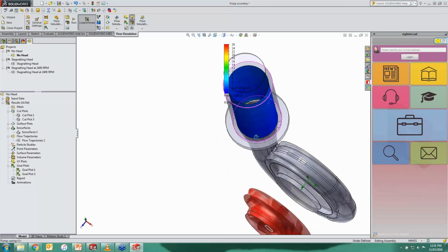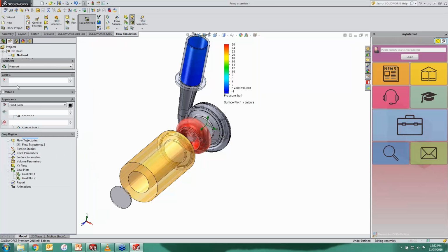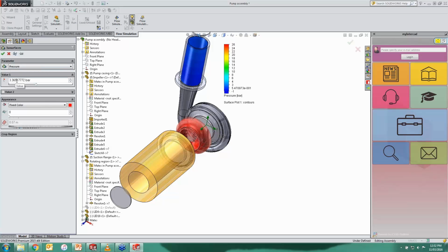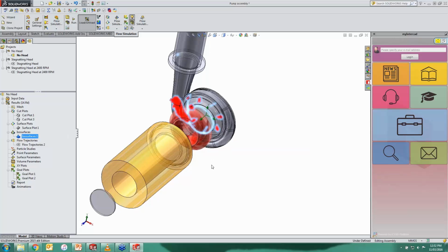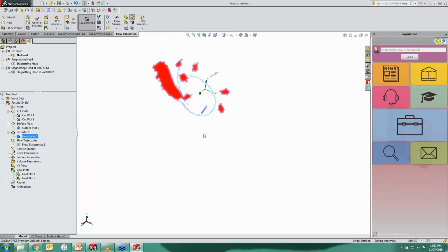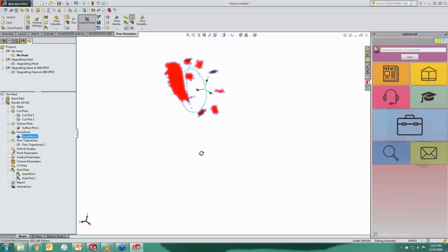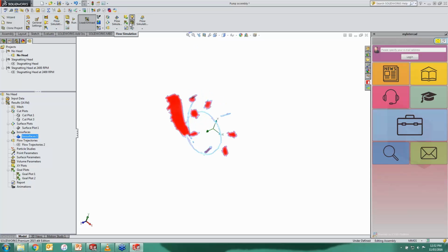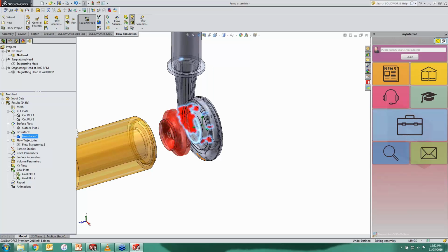The other option you have is to create isosurfaces, surfaces which have some property of some value. Like, you can go to pressure, there is 3 bars, and I would like to show them here. Click OK, and let me hide this one and show the isosurfaces. Now, if I hide my model, these are the regions where I have that much pressure, highlighted in this color. Either I can have the model here and you can see it. As many isosurfaces as you like, you can create them.